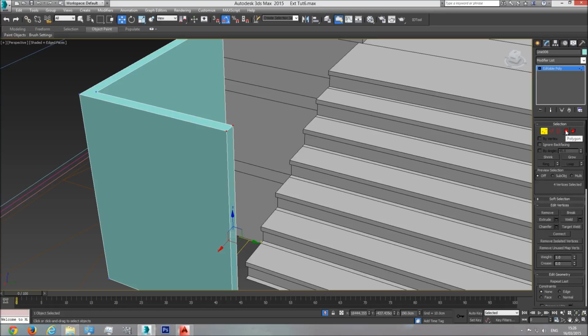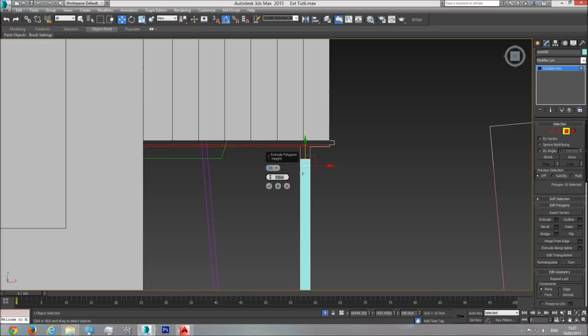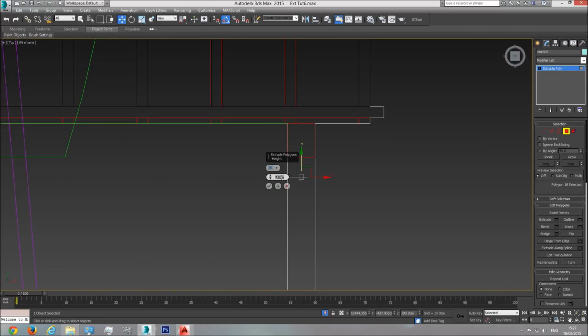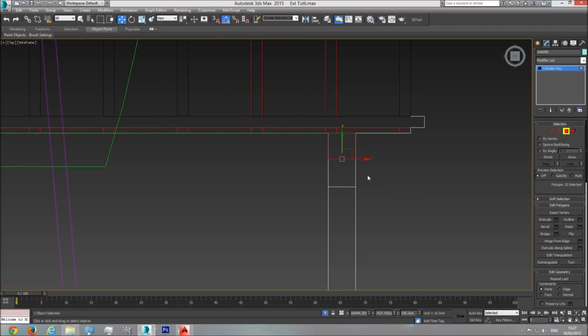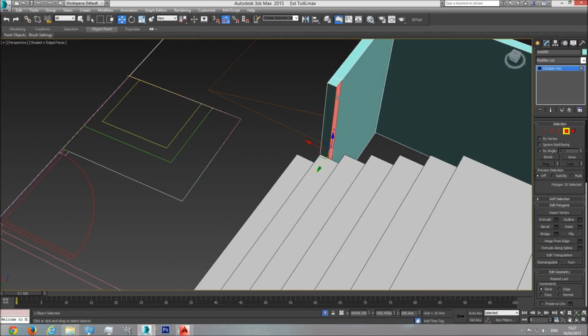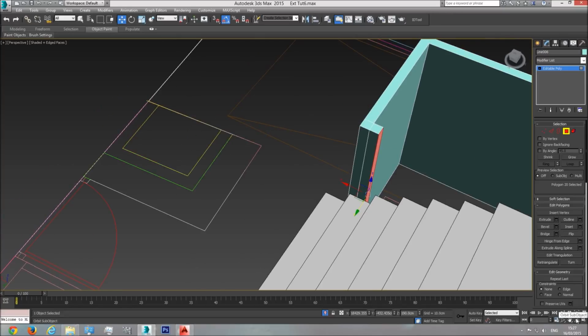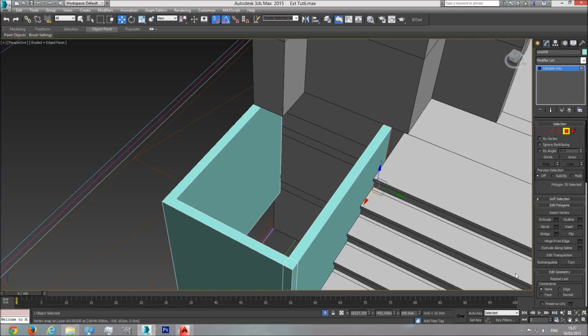So I'm going to select this polygon here, going to extrude it by 7 centimeters. I think it needs to be like a square here, so I'm guessing it's 10 centimeters. Yeah, that's fine. And we're going to take this polygon here and take him back to the house. So I just extruded 10 centimeters, and I'm going to click on snap toggle and move this polygon to the house itself.